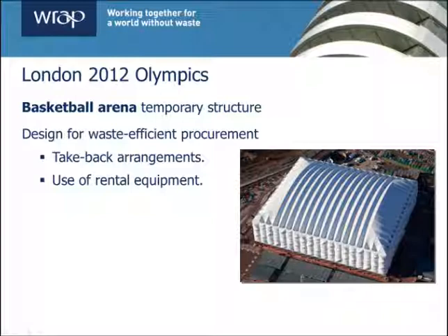The weight of the structural steel frame was reduced by 100 tons, approximately 10% of the total, during the detailed design period by selecting lighter members, designing to a higher percentage of structural capacity, and minimizing offcuts during fabrication of the frame components. This produced a saving of £60,000 in material costs.